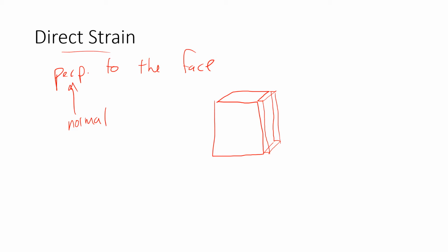All right, so strain is going to be measured by having the change in length divided by the original length. Okay, so here is going to be your original length. It's that distance there. And this guy right here is going to be the change in length, so delta L. All right, the symbol for strain is going to be this guy. It is an epsilon.